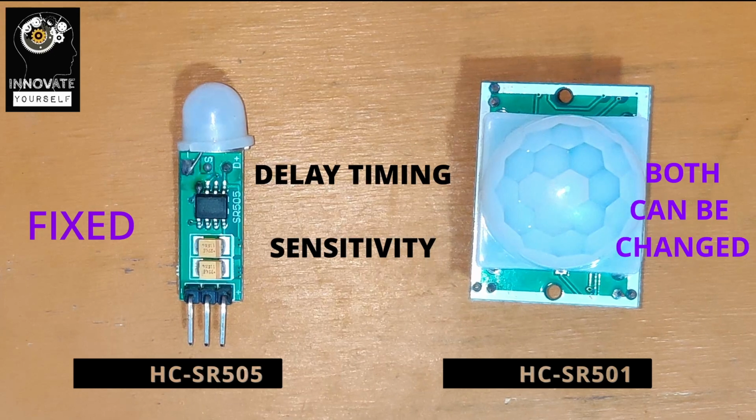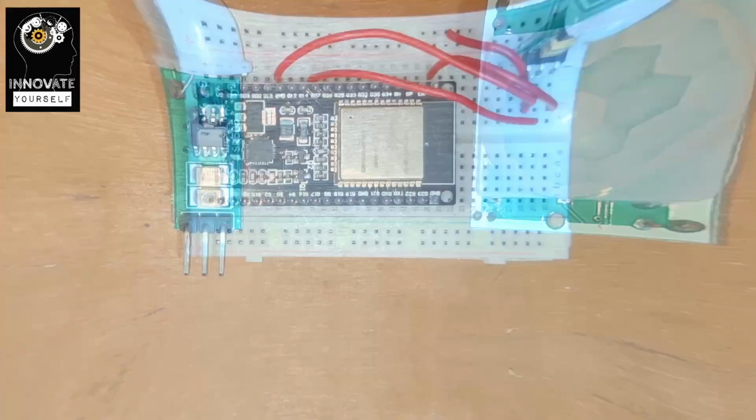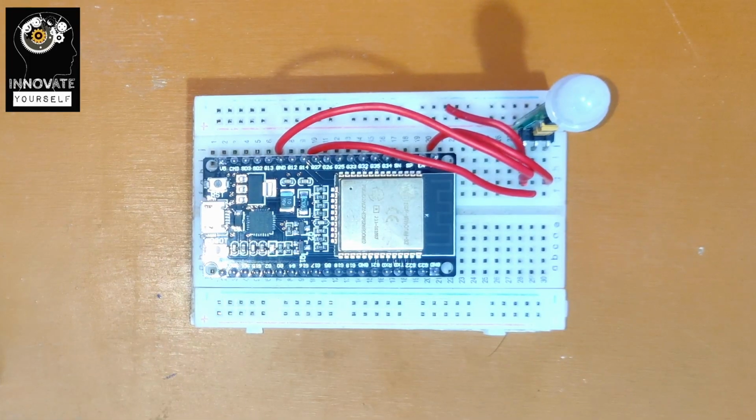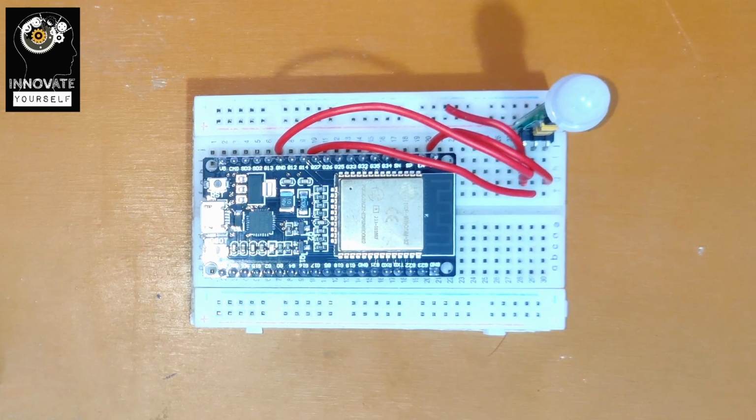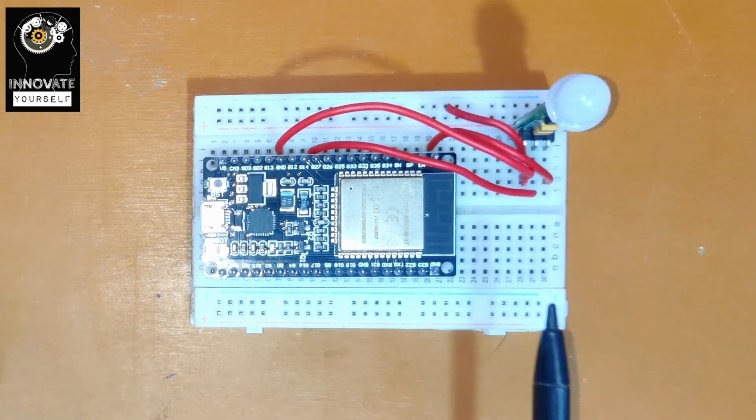Let's proceed further and let me make the final connections so that I can show you how we are going to work with this. All right everyone, you can see that the connections are already made between the ESP32 and your PIR sensor, which is the HC-SR505. The connections are really easy, so you can do it very easily. But still, let me quickly tell you where exactly we have made the connections. The first thing is that the PIR sensor has 3 GPIO pins, or let's say 3 pinouts.